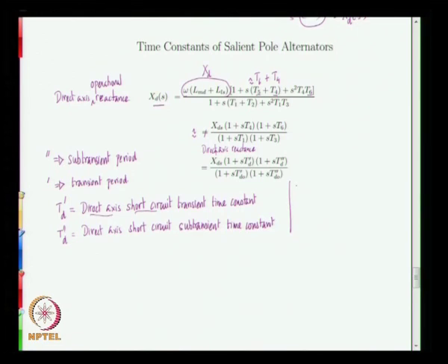If you look at the alternator rotating at synchronous speed, at synchronous speed there is no relative movement between the rotating magnetic field and the rotor itself. The rotating magnetic field rotates at synchronous speed, and the rotor also rotates at synchronous speed.